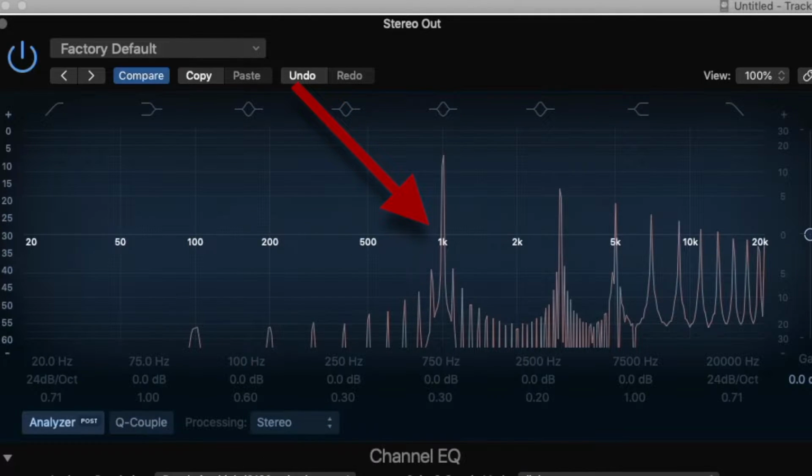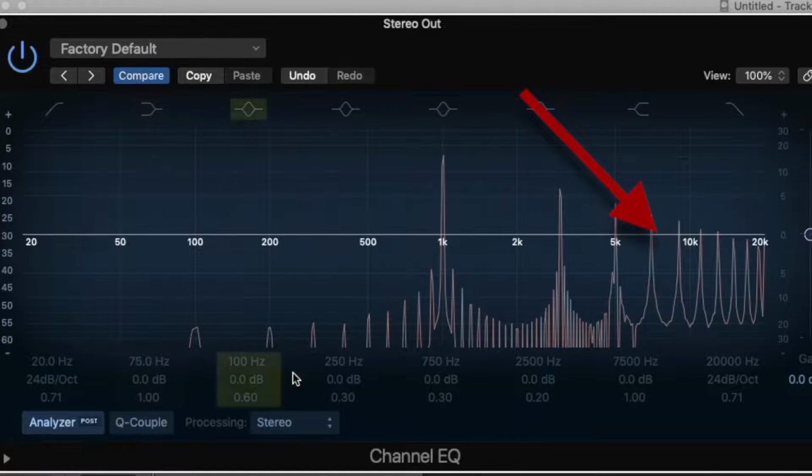Fundamental harmonic is at 1 kilohertz, and then we just have odd order harmonics going up. For measuring purposes, we will also be concerned with the even order harmonics, but this is a symmetrical signal, so we're just going to get odd stuff. That's music crap. I won't deal with that right now.